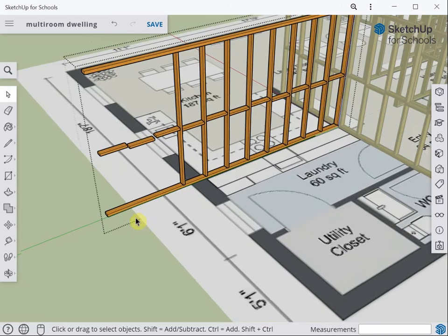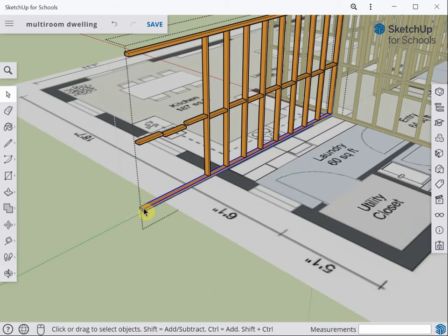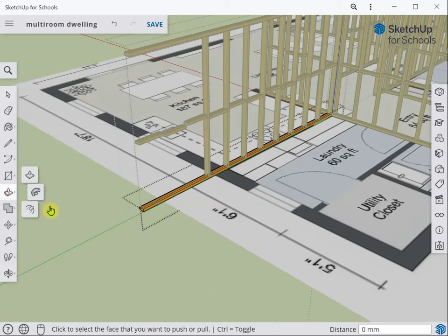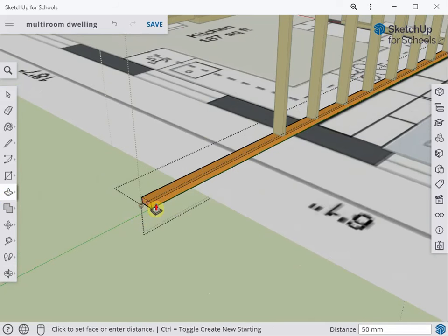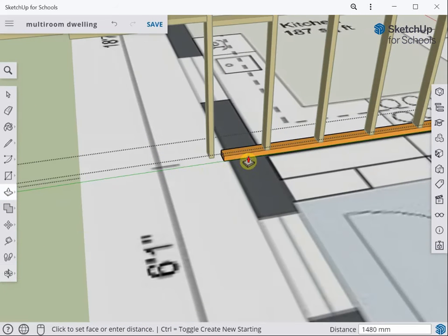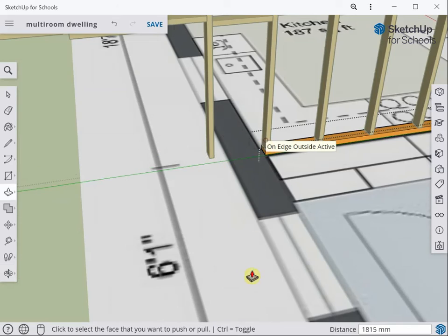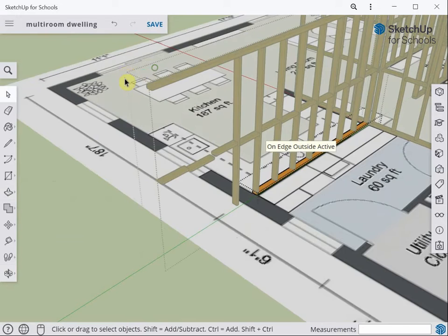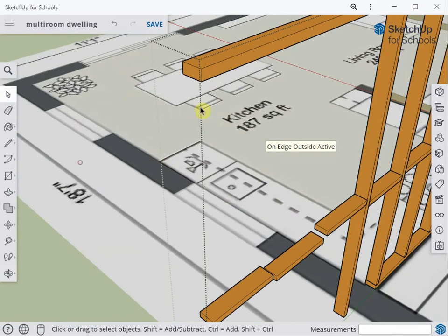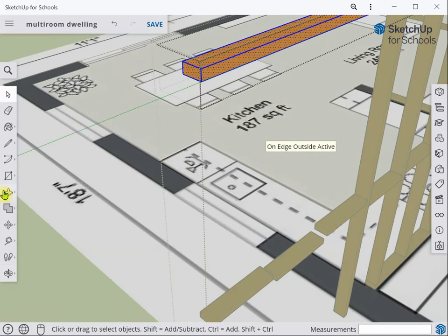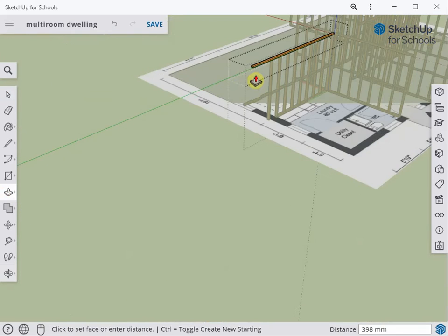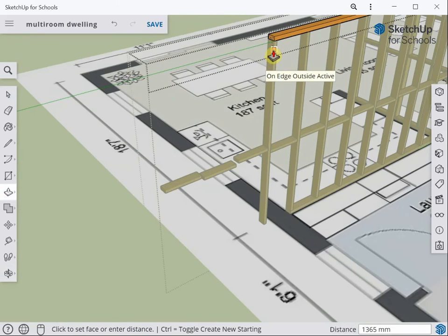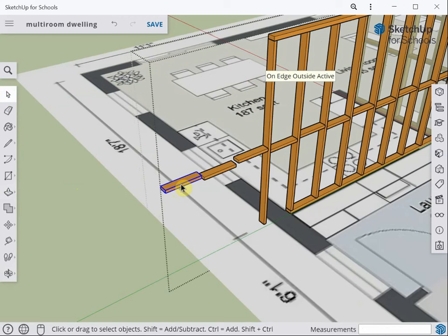Okay, you can use things like double clicking on there, and then you can use the push and pull tool to move that into position, and just modify the walls to get them how you'd like them to look, the correct length and so on. All right, so that's the process of starting to clean up and make the walls the correct length.